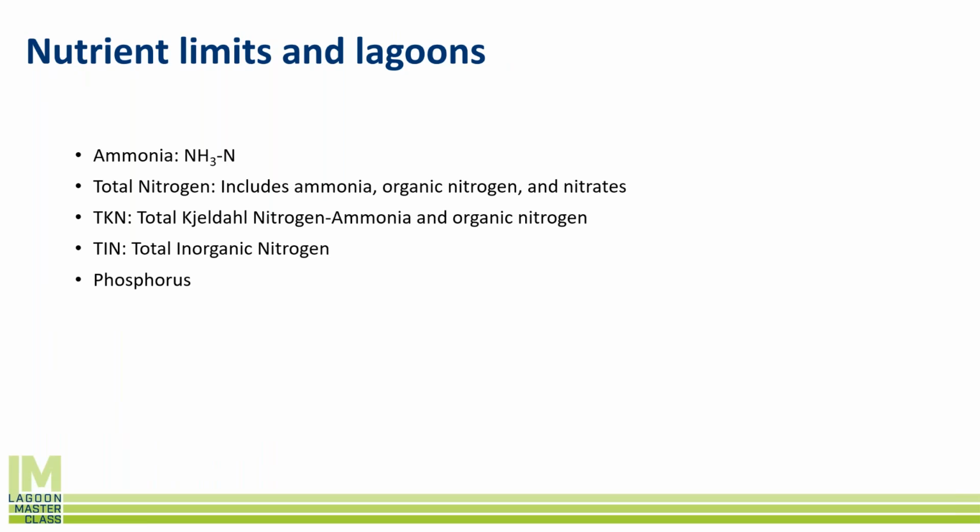Once that total Kjeldahl nitrogen, or TKN, gets into the wastewater treatment plant, that's going to break down and become ammonia. So in a lot of states now, when we design our wastewater treatment facilities, they want us to design off of TKN, not off of ammonia, to make sure that we actually have the capacity inside of the wastewater lagoon to break down all the TKN into ammonia, so we don't undersupply oxygen to the system.